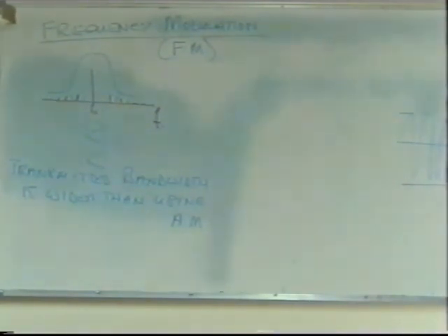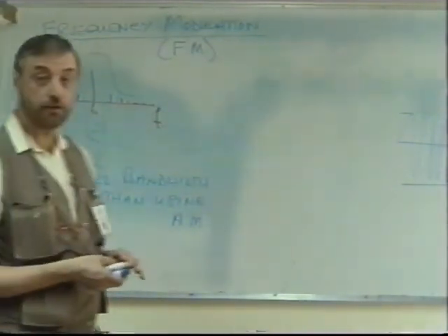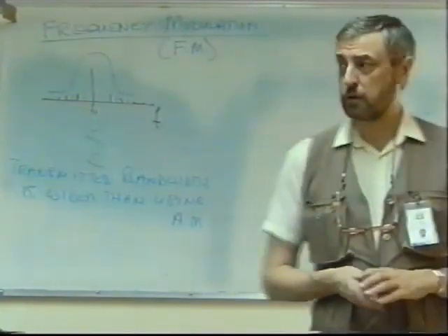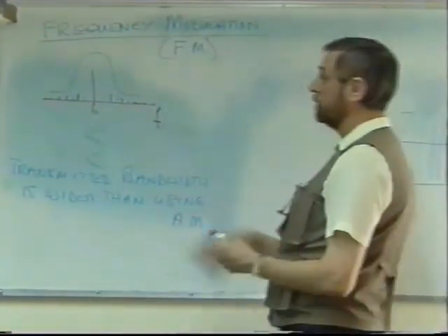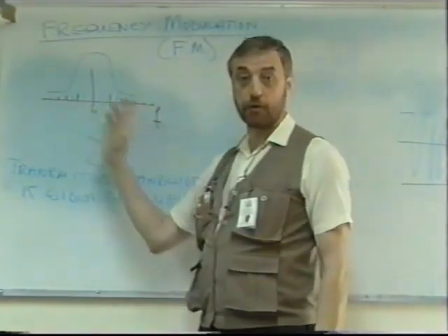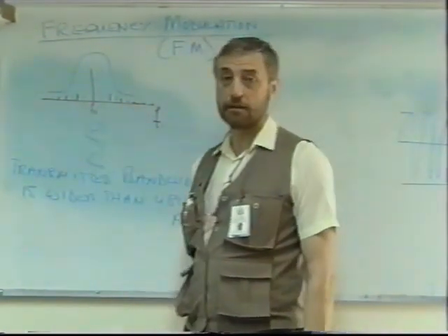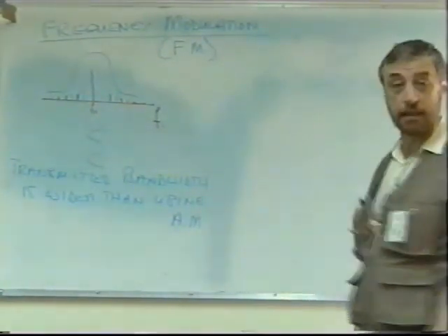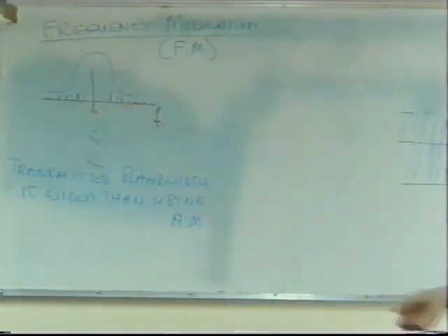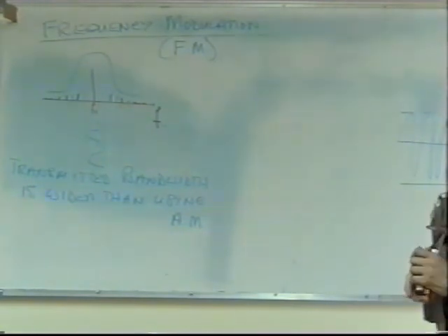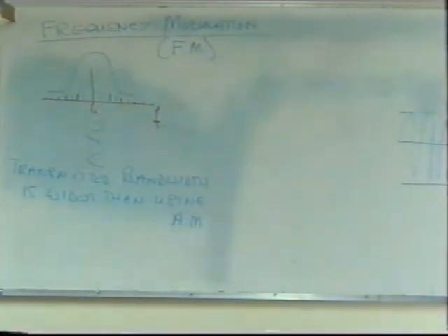There is no cutoff. I'm sorry, if you know the amplitude modulation criteria, it depends on the amplitude of the signal. Oh yeah, if you overmodulate, you're talking about. Yeah, that's true. But of course, again here, the more you modulate, the more frequencies you're going to generate. So you would end up distorting the signal anyway if you overmodulate, but maybe not to the same extent as you would if you cut off on a carrier.